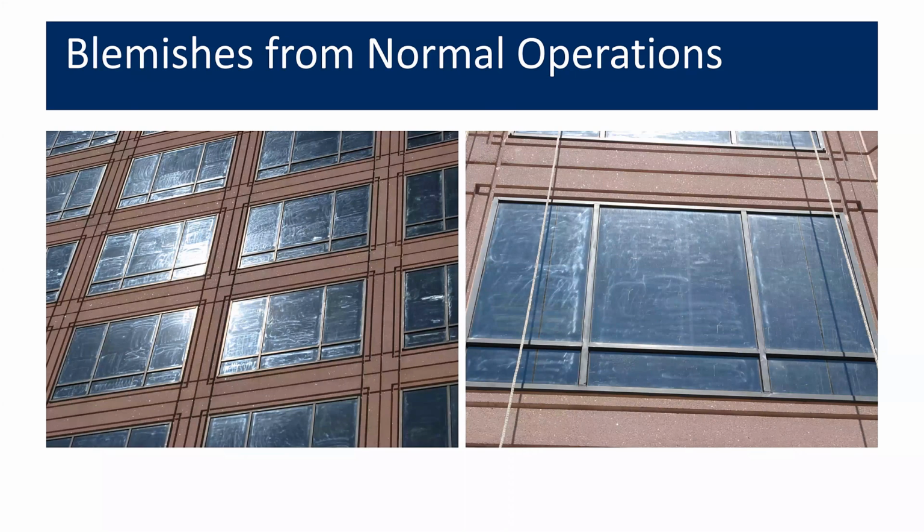So in the process of trying to remove these types of stains, we've encountered buildings like this in the past where a proprietary glass cleaning compound was used and resulted in an unwanted artistic effect, as you can see. And many of those scratches are barely perceptible except under direct reflected sunlight, so it can be tricky to pick those up.